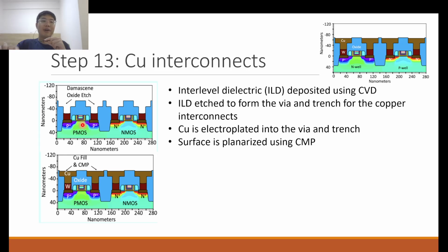Actually, there's quite a bit of technique that goes into etching the trench and the via. Because after all, it's not just a straight line down, right? You have to get this profile, which I may cover in a future video, I may not, but definitely not in this video. But there's some technique to achieving this profile in the dual Damascene process. But basically, this profile is created.